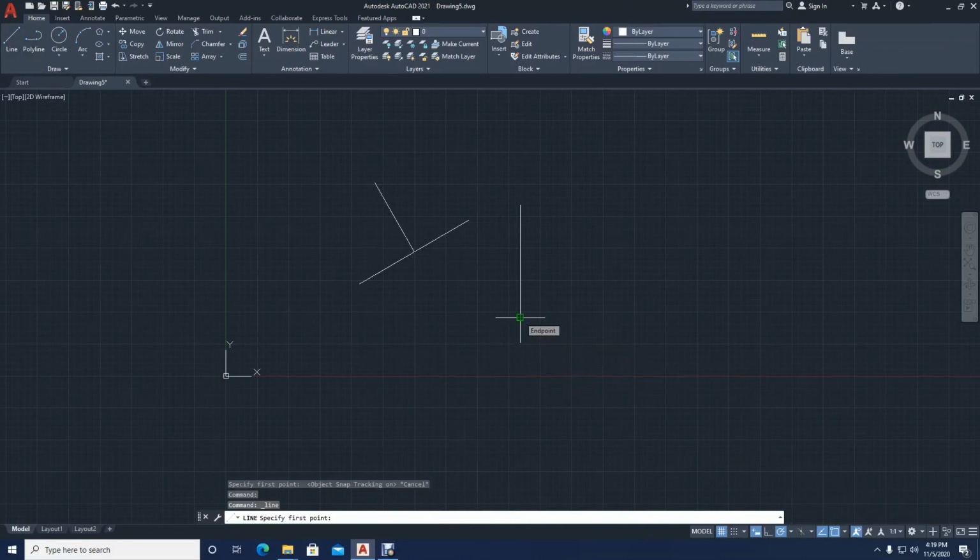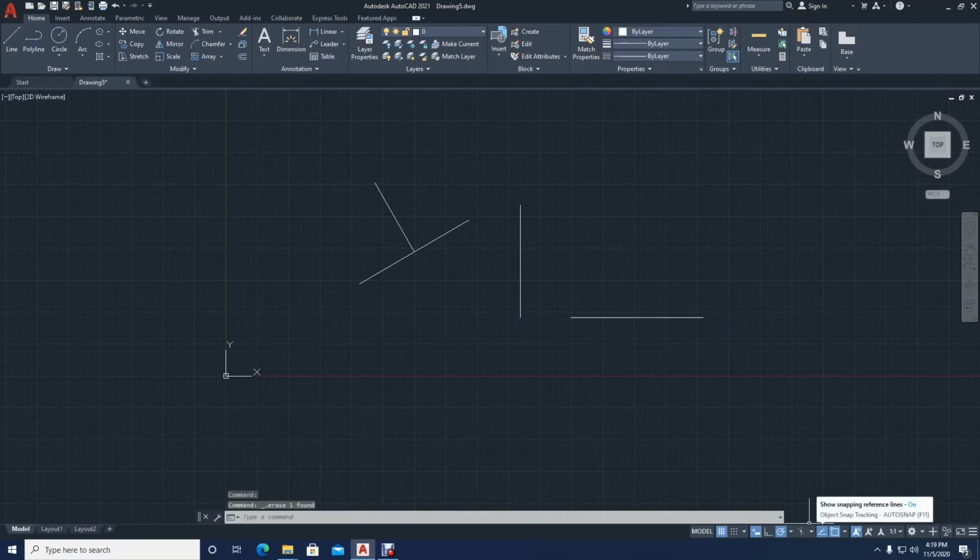I've not clicked the mouse as yet. Then pull it in the direction where I want the line to start. And the distance, I'm going to now type 20, as I want it to start 20 millimeters from that point. Once I've pressed enter, the line will start there. I could have just selected line, drawn a line 20 in that direction, pressed enter, proceeded to draw the actual line that I want, then deleted the first line. But that is more work. This is a very handy feature.